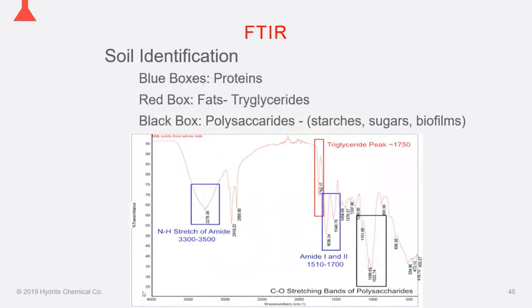So a similar method that doesn't necessarily require such advanced techniques is FTIR, and this is going to use your infrared band wavelengths. This is going to be basically using your low frequency levels of light, which is going to tell us something not necessarily based on the atoms, but on the bond types and their structure that make up the molecules that might be in the foulant. And again, this is going to be a comparison between the membrane that hasn't been used, which we'll have to get from the membrane manufacturer, and the one that is probably fouled.